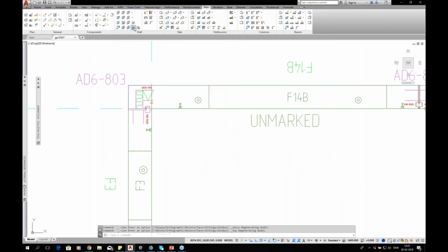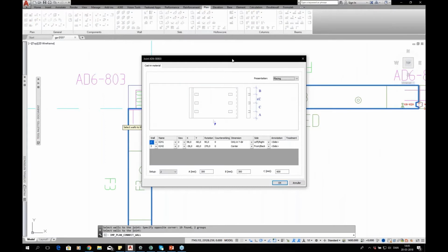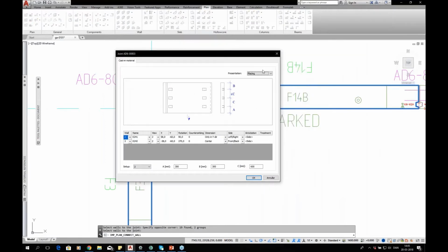So when doing the connections, I use the connect command, of course. And in this case, I only have one connection. And this connection is for my specific point here, a wire loop connection with a center distance of 600. I can change the center distance, or I can change the start point from top to bottom, for example, or do different setups, let's say I want 5 in each, or I want one per 400 millimeters, however you like it to be.